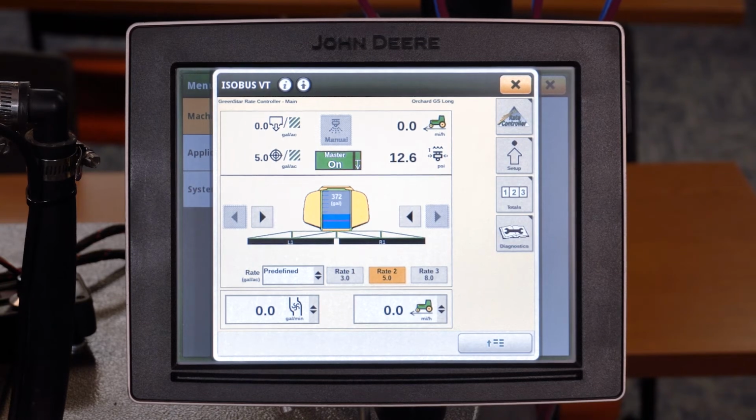After you've checked those things, then you can check, is the pump running? This isn't always as easy as it seems. There can be a lot of noise and vibration with everything else running. On an electric pump, go back and feel the pump, unplug the pump, see if you can tell if it's actually running. On a hydraulic pump, same thing. Feel the pump, unplug the PWM connector, verify that the pump is running.